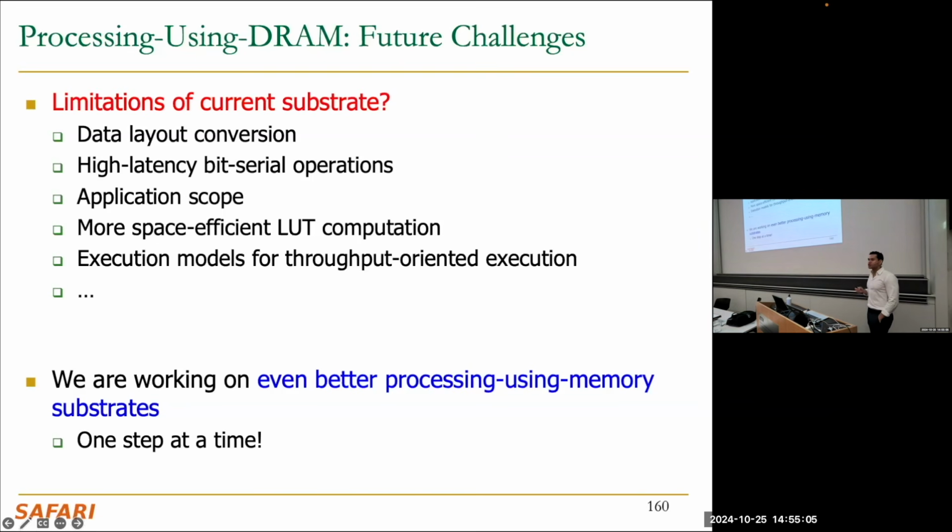This is not only true for processing-using-DRAM, or you might think, oh, this is an artifact of your own stupidity, you created this problem in SIMDRAM and are just following up on it. It is not only architectures like SIMDRAM or MIMDRAM that follow this protocol, and it's not only DRAM-based processing-using-memory architectures. SRAM-based processing-using-memory architectures suffer from exactly the same problem, because they also need to transpose the data and operate in a bit-serial manner if they don't want to blow up the area with interconnect.